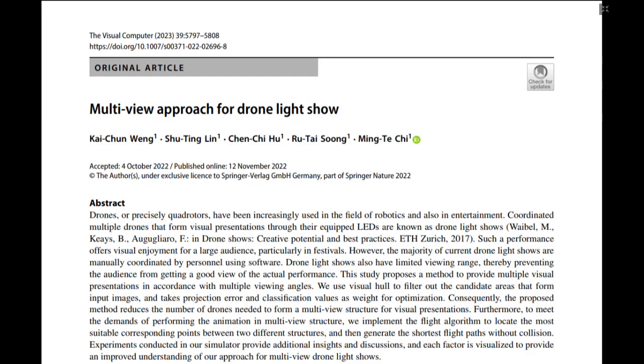For drones that are not assigned to a destination, their lights are turned off and they remain idle at their current position. If the next structure requires these drones to move, they can move early to their respective destination points to await further instructions. Hence, the position change and light status of each drone during the entire show are generated to provide simulation for path planning.